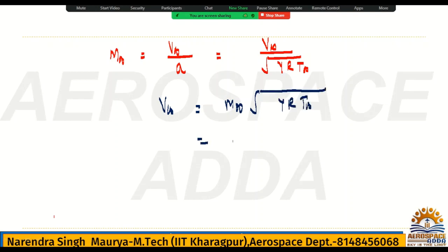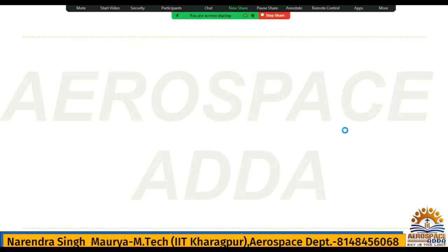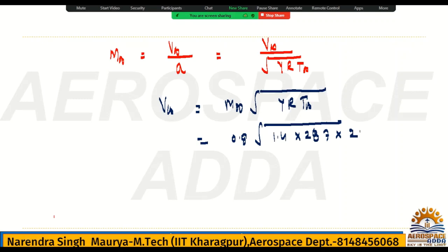Okay, so Mach is what? 0.8 you have. Gamma 1.4, considering it as air. R is 287. Temperature you had calculated, it is 223. So write this value: 1.4 multiplied by 287 multiplied by 223, take root of it, multiply by 0.8.